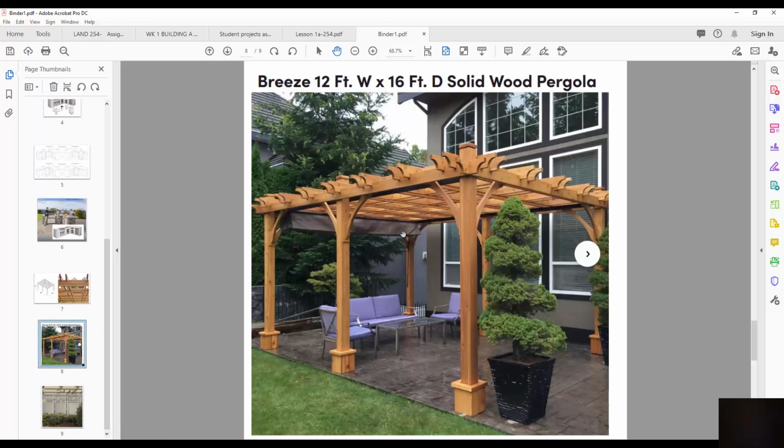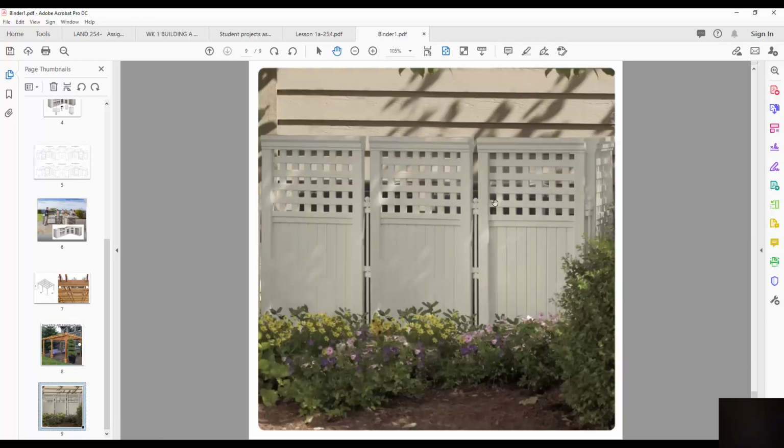Remember, as part of the outline, I mentioned that these posts cannot be any further than 14 feet apart. It's to help us when we get into the documentation of using the Ontario Building Code to actually design this to code. And then I've got another element there as a screen that is separate, so something that doesn't actually have a fixed planter in place as well. So I want this level of documentation to support anything that you draw in your particular project.